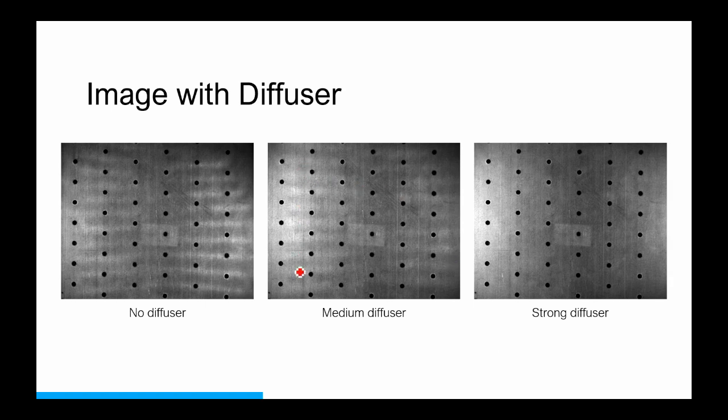You can see that it definitely improved the sample, but there still are these LEDs shining that are causing a little bit of hotspot, a less uniform image. So then I can step up to my opaline diffuser, and that's more the diffuser level of a backlight, which needs to be extremely uniform. You lose the power of the light because you're diffusing it much more. You don't have the same intensity, but you have significantly more uniformity. I don't have those LED lights shining anymore. It's a much more uniform image. So having a diffuser will help a lot in certain scenarios, but it doesn't necessarily guarantee that it will remove the glare altogether.